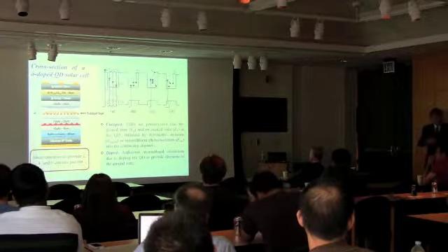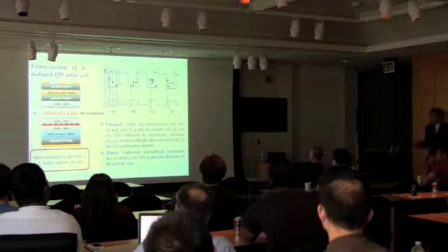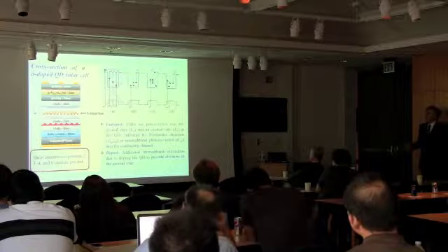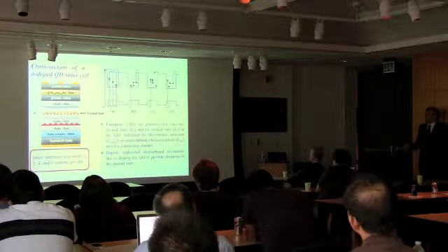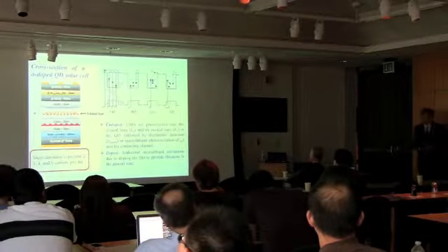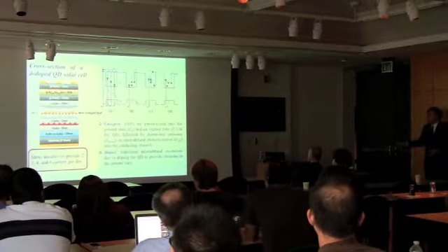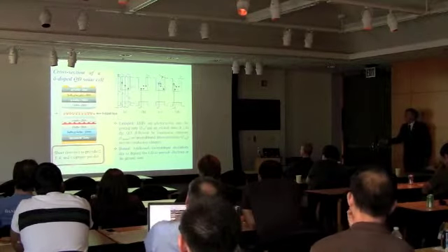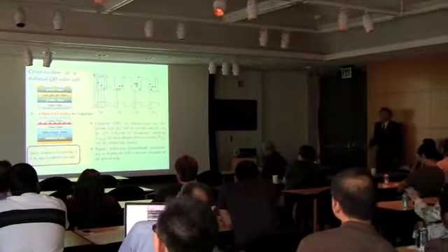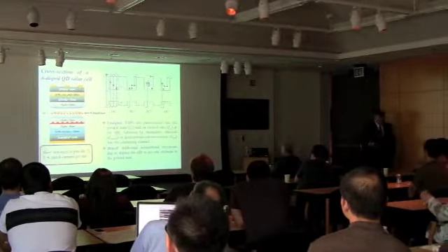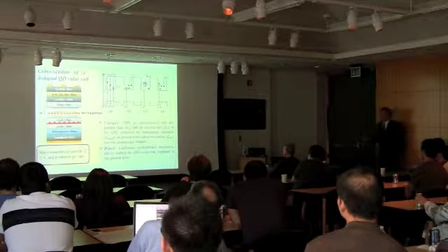That was not in the original design, and this new mechanism is the following: when we have, for example, absorption of light in the dots, with an electron somewhere in a higher level, then this electron, as I already have electrons initially, which I put in during the process of growth, can lose its energy going down, but give that energy to another electron that goes up. And this is one of the things that can increase the contribution to the current.